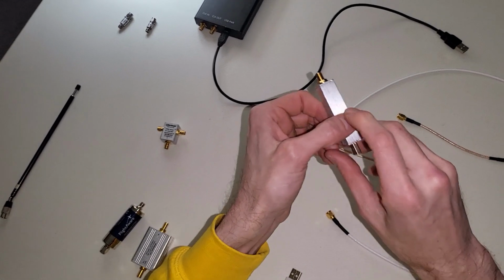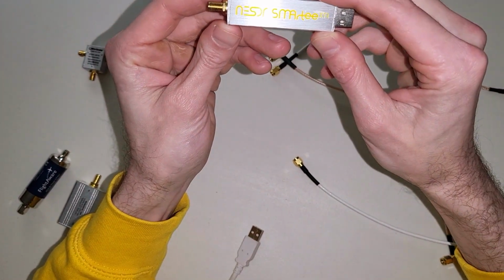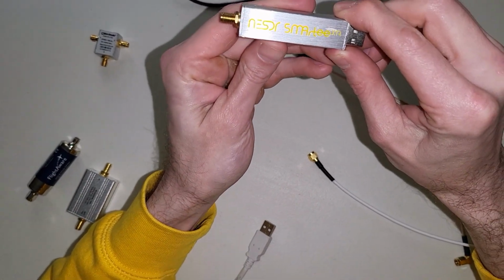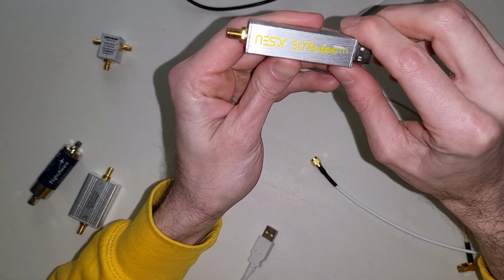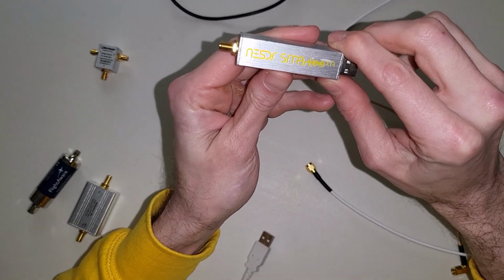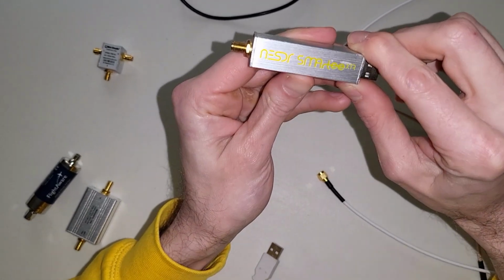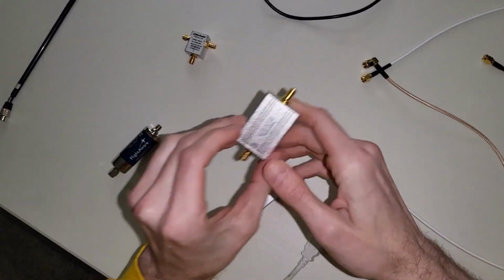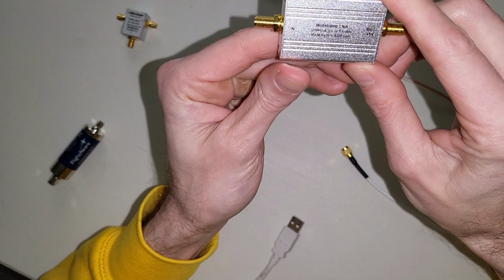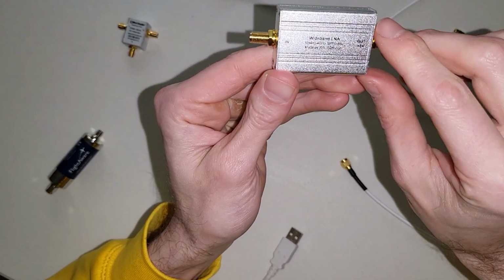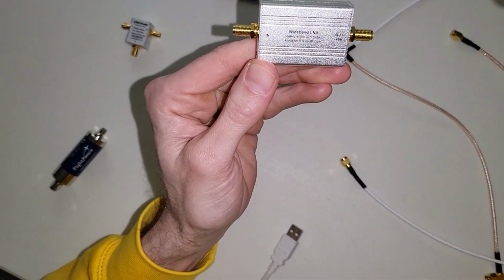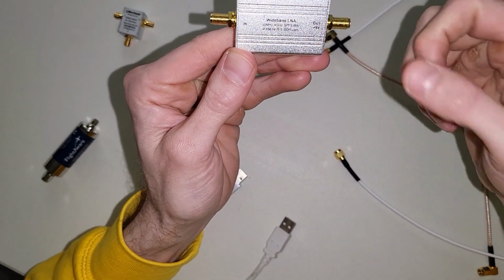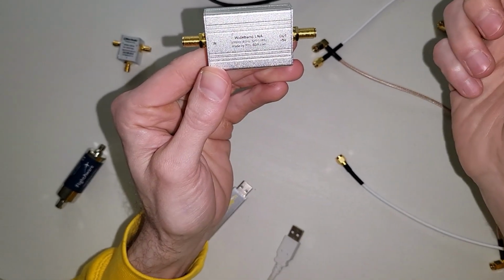The first device we're going to look at is a RTL-SDR dongle. This is what we're going to use to receive the ADS-B signals, and this is a particular kind of RTL-SDR dongle that has a device in it called a bias T. And the reason for that will become clear once I explain the next device, which is a low noise amplifier. This is going to amplify the signals that we receive over the air, and it's going to allow us to receive weaker signals than we might have been able to otherwise.